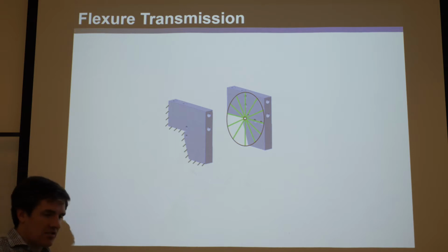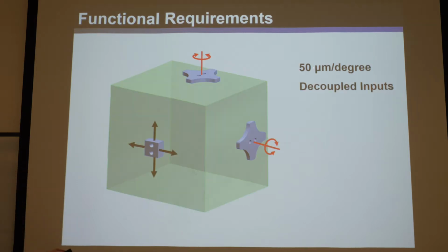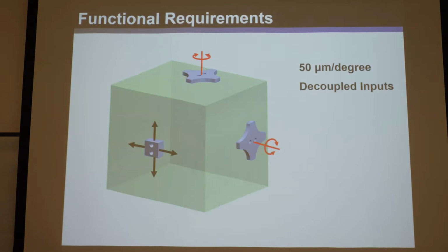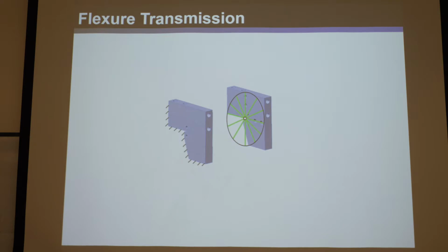disk of intersecting screws, because the transmission ratio, by the way, is the same. It's 50 microns per degree for both of them. So let's do a disk that has a pitch of 50 microns per degree, essentially, right? So that transmission ratio that you want, 50 microns per degree of rotation. That's a pitch. So you get screws of all that same pitch, okay? And let's design something that achieves that, okay?